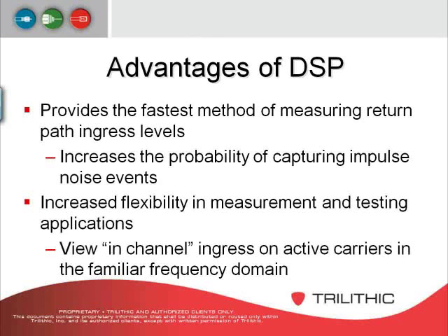So the thing is, even with DSP technology, let's say you have an area where your modem carries at 30 megahertz. With DSP technology, we have the ability of removing that modem carrier, so the only thing that's left is just the noise floor. So it makes it real good, because as long as that modem carrier is there, if there's ingress falling up under that carrier, you're not going to see it.